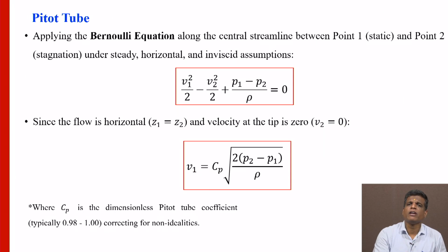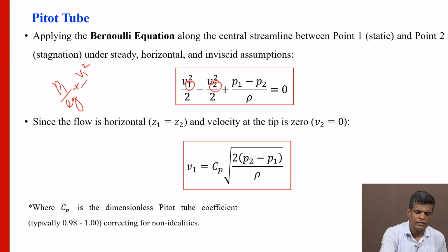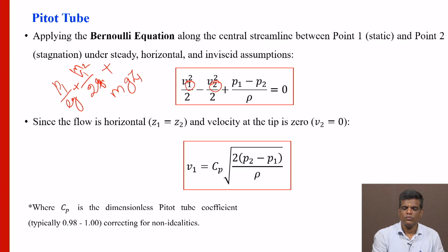So, this is a very famous Bernoulli equation. Normally we use, first, the pressure energy P1 by rho g at point 1, because there are 2 points, one is point 1 and another is point 2, location 1 and location 2. So, P1 by rho g, then V1 square by 2g, then another is the potential energy. We always write it as z1.